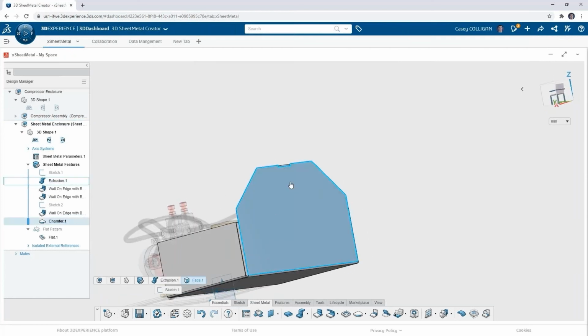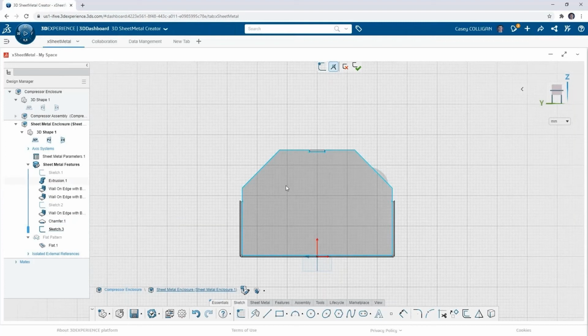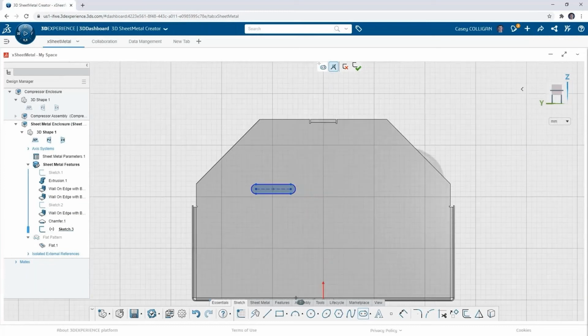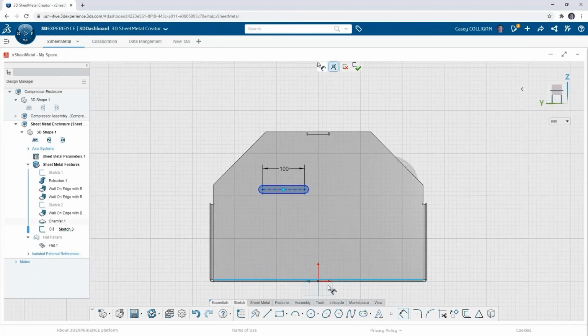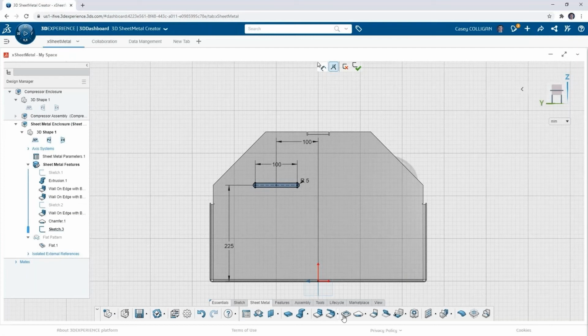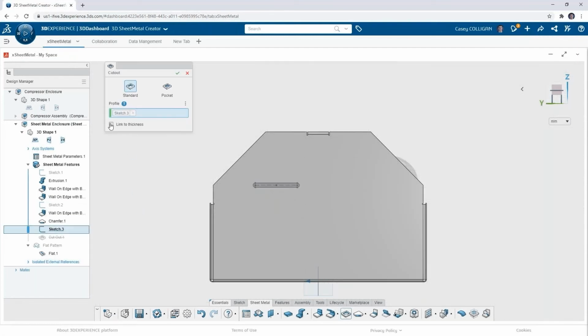Now let's say I want to add in some type of vents on the back for some airflow. I can just start off just like we were doing inside of SolidWorks. It's a simple little slot cut. You can kind of see as I add this in here an idea of what I'm going to be doing next. I'm going to be positioning this in a specific location, so that I only have to sketch one, and then I can leverage patterns to capture the rest. I'm just going to position my first profile here for my cut and just do a normal cut.